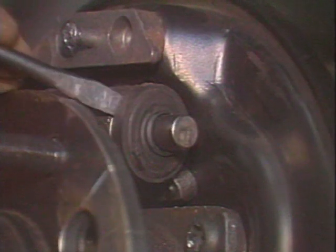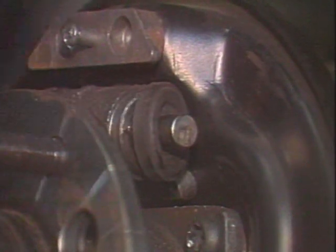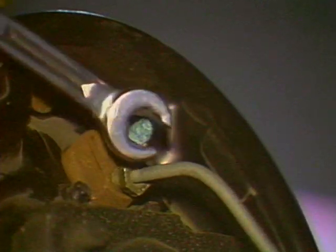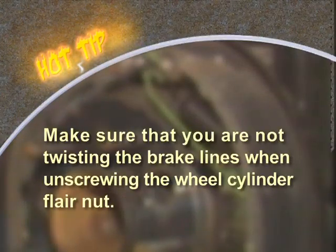If you find fluid leakage after pulling back one of the boots, replace the wheel cylinders. To remove a wheel cylinder for replacement, unscrew its brake line and the fasteners securing it to the backing plate.